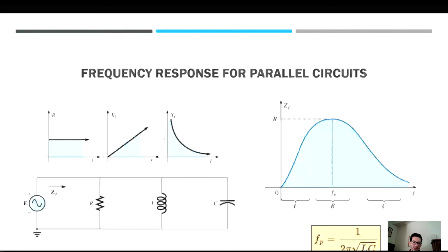So when you have a circuit in parallel where your initial wave has frequencies that are varying, so that your frequency goes from one value to the next value, but it's not a sudden change, it's an incremental change, kind of like they're showing here, the response of each passive element is different. We saw this before. The response is exactly the same as in series because the response depends on the element, not on the circuit. The combination of the elements is what makes the response of the total circuit, and that's what we want to see next.